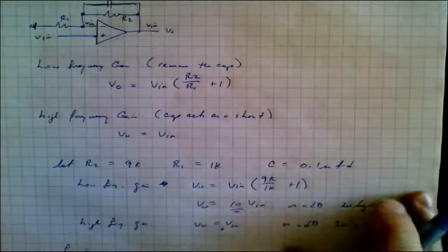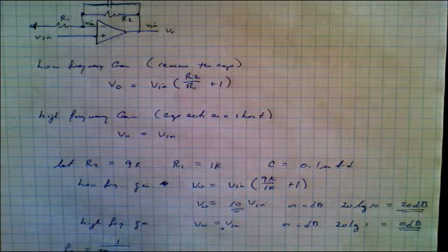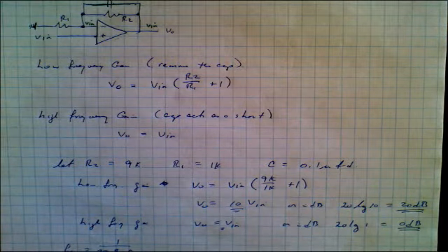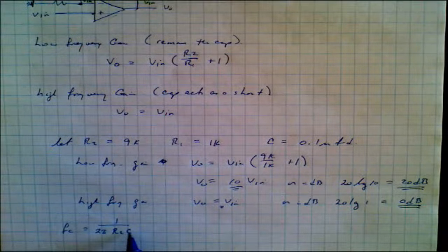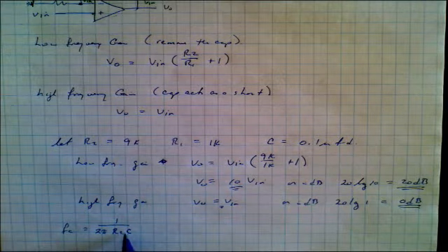And so the corner frequency is simply 1 over 2 pi, in this case R2C. The corner frequency occurs when the reactance of the capacitance becomes the same as the value of the resistance. And that's where the change begins to occur. It stops acting like a resistor and starts acting more like a capacitor, and the roll-off continues.